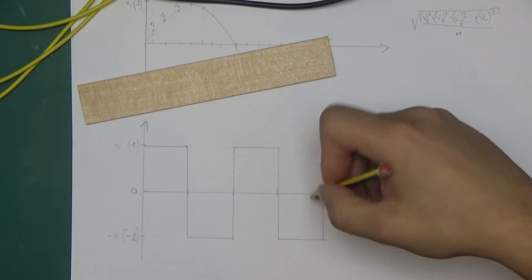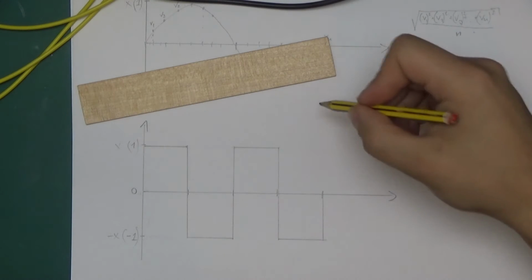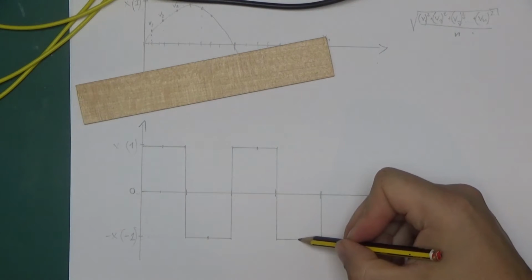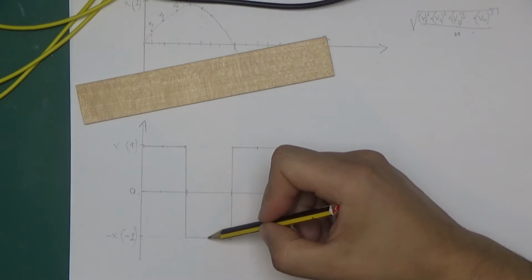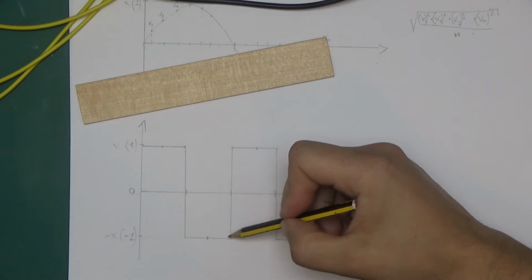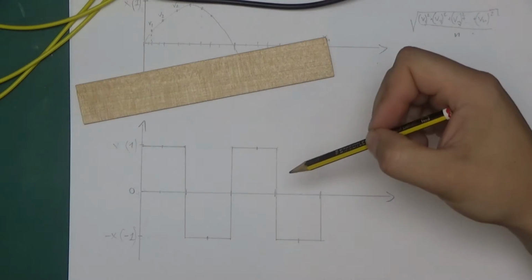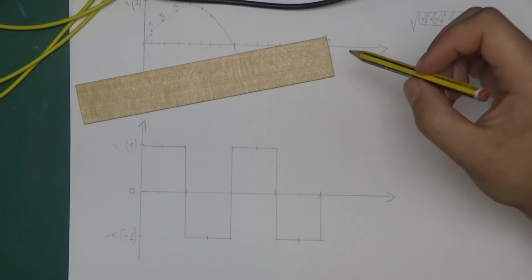RMS value of this, to get it using this approximation form, it's actually quite easy. All we have to do is take a measurement at each of those points, because the waveform is not changing anywhere in between. If we take a measurement here, it kind of covers this area and it covers this area, and then the duty cycle also doesn't matter in a case of a symmetrical waveform like this. I'll show that in a moment why.